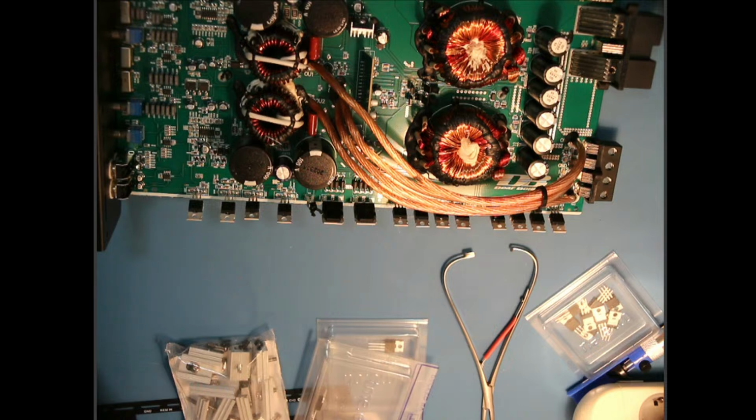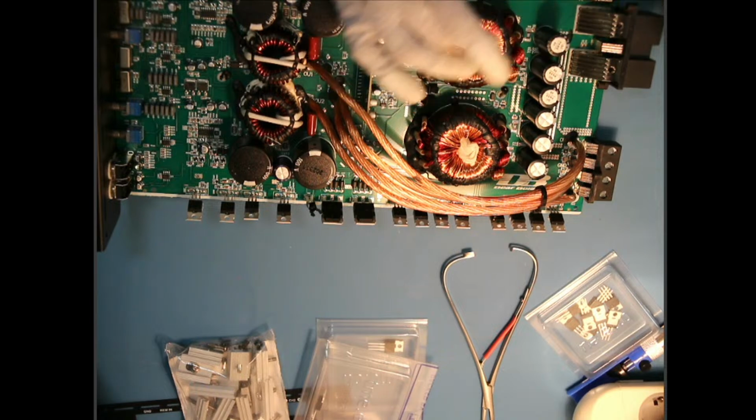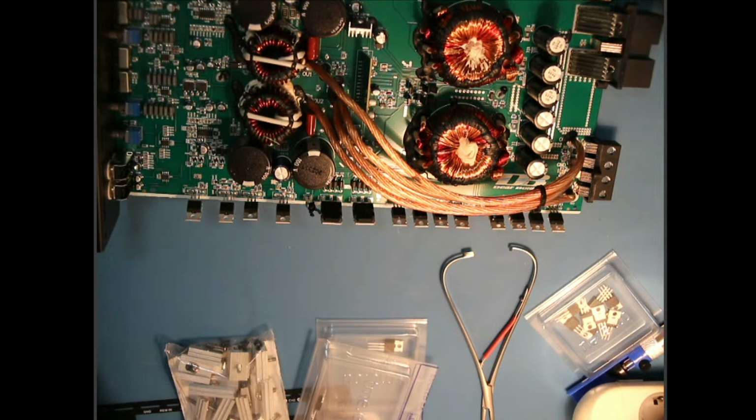So there, 2SC3228 is what 4 of them are. 3228, 3228. I don't think I have to match their gains, right? Because they're just either driving the output MOSFETs or something. In the power supply, I don't think their gain actually matters all that much.